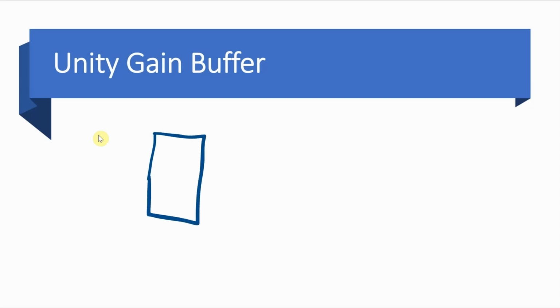And so we will be providing exactly the right voltage to the load without drawing too much current from the voltage source. Also consider the case where you have a microcontroller of some kind, and on the digital output pins, you have a fairly heavy load, a fairly big load connected to it. And if that load draws too much current, more than the microcontroller can provide, you're going to run into some potential problems. However, if you put a unity gain buffer between the microcontroller pin and the load, then as long as the current drive of the op-amp isn't exceeded, it will be possible to provide enough current for that load. And you can find lots of op-amps with a higher current drive capability than a microcontroller.